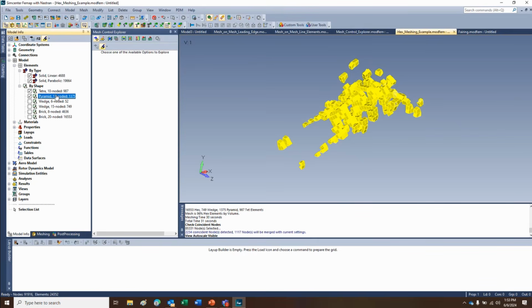And again, this was version 1.2 of this semi or hex dominant mesher that we got from another piece of Siemens, the folks that write Flow EFD. So this mesh is 96% hex elements by volume, and we meshed a 3-part assembly without having to subdivide it at all.